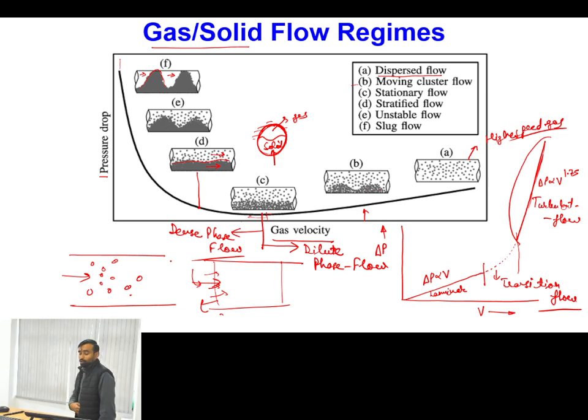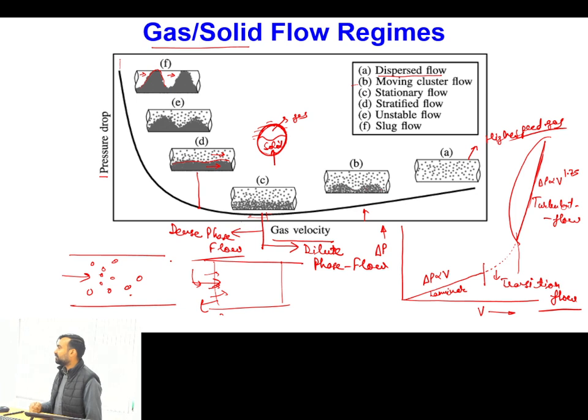So though the belt conveyor or other modes which have interaction of particles with the surrounding atmosphere may consume less energy in comparison to this type of transport of solid particles inside a pipeline using pressurized gas, they are not good for the environment. So that's why majorly in industrial systems, a pneumatic conveying pipeline is used for transporting fine solid particles.